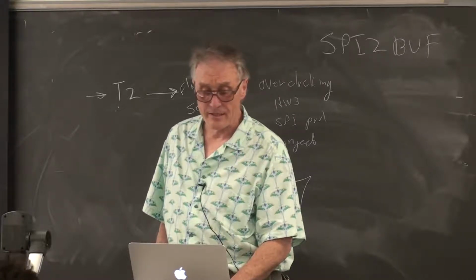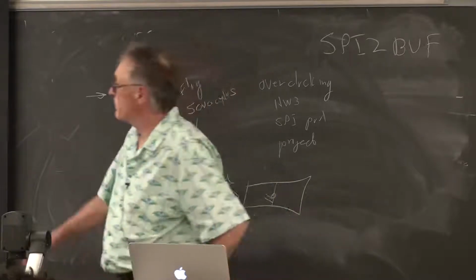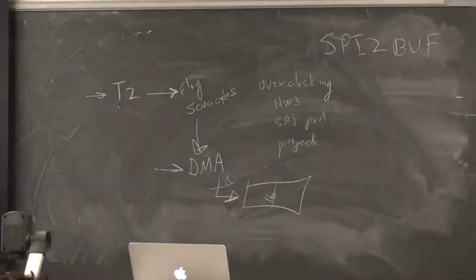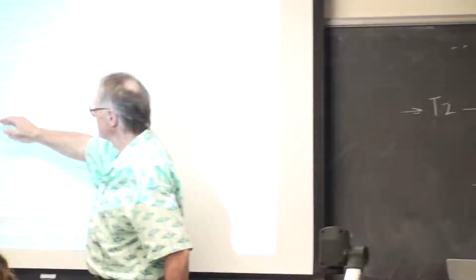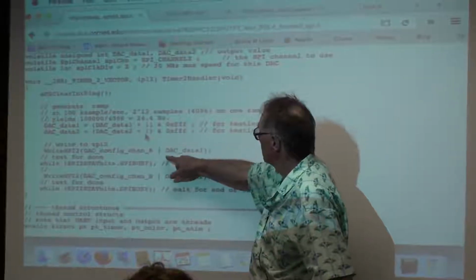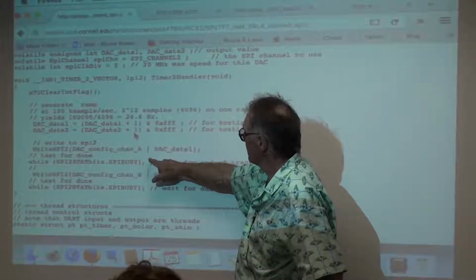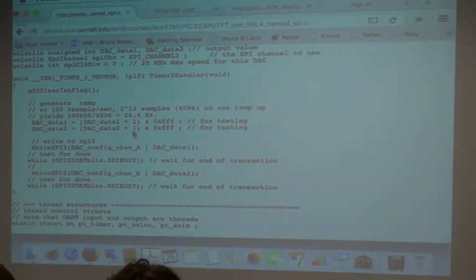the contents of the interrupt, what interrupt? There's no interrupt. With a DMA controller, this interrupt is going to be gone. There will be no transmit. There will be no check to see if the bits are ready, if the channel is ready.